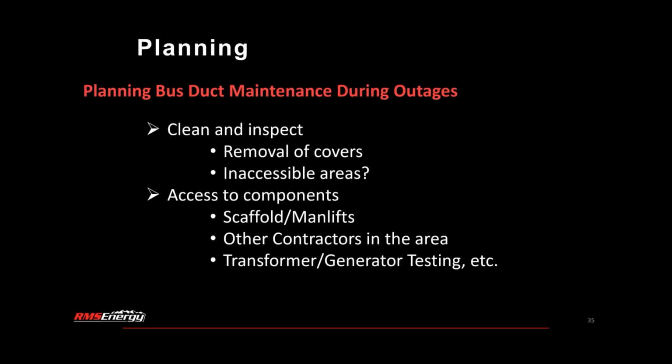What other contractors are going to be in the area? Is everyone going to be able to work on the equipment at the same time, or do you need to stage access? And then, what other scopes are in the area? Transformer and generator testing can introduce high voltage into those terminations. So you want to ensure you don't have two contractors working on top of each other, where you can introduce high voltage into an area where someone's working.